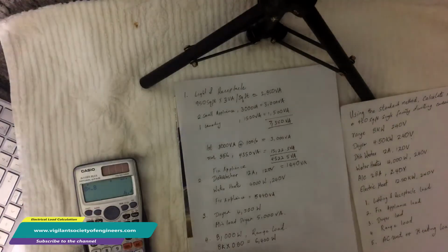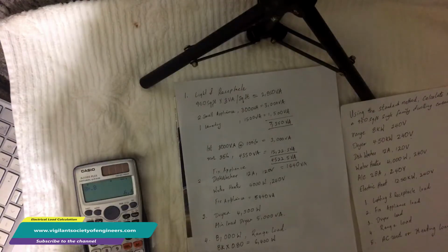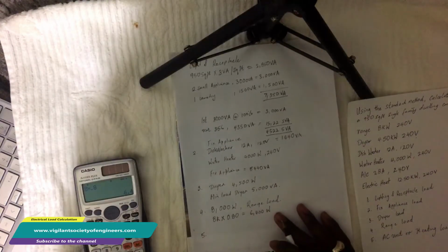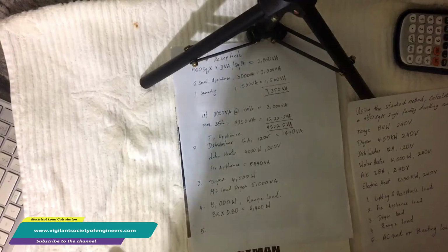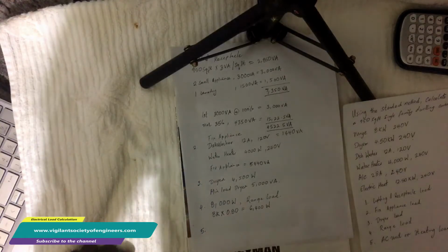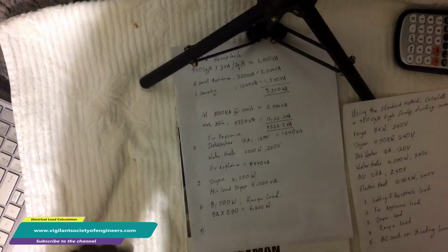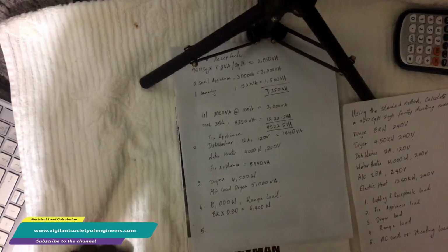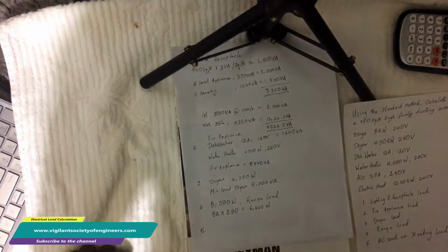Right, and then the next one we're going to focus on is the AC unit or the heating load. So let us examine the AC or the heating load. Remember, when it comes to AC or heating load, we take either of the largest value. The demand would be based upon the maximum capacity of the load. So we're going to take the highest value, because when it comes to these units, you can only run one at a time.